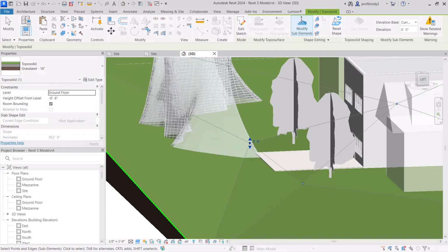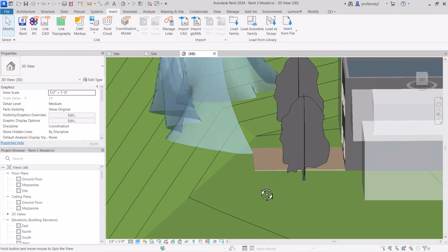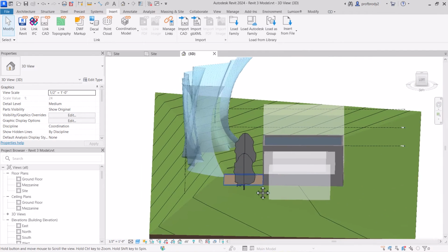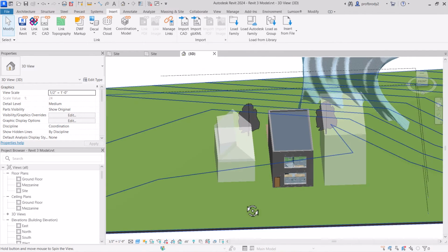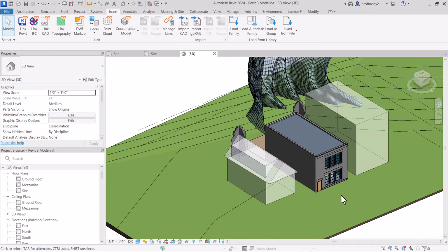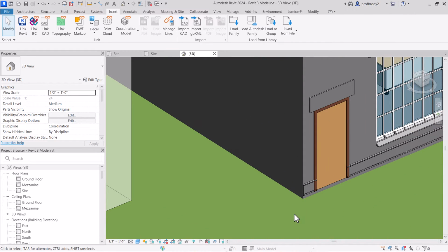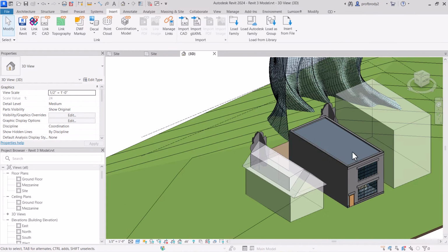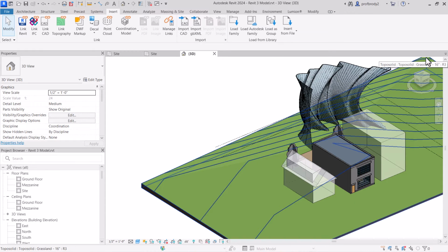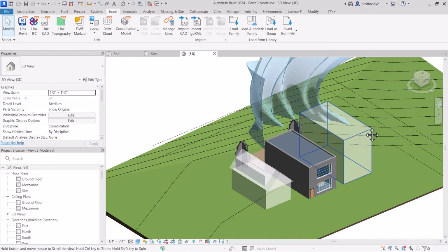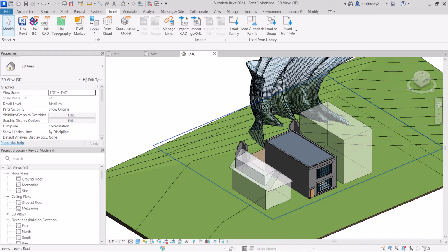Again, those of you familiar with SketchUp know that once you start modifying organic shapes in 3D, it can get pretty complicated. So on our site, the big thing is that the site slab should be about 6 inches below the surface of the landing of the door, which we handled by moving the whole site. And I would like you to try and create one point that's taller than the others. And again, the big thing is getting used to experimenting with these site warping tools.